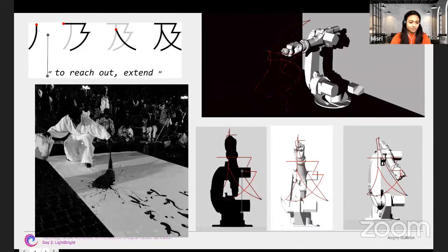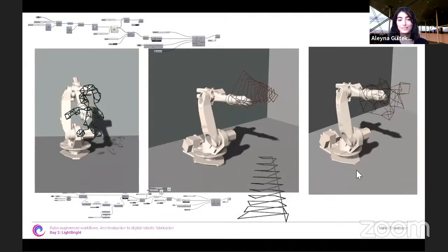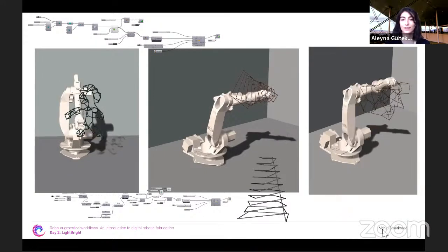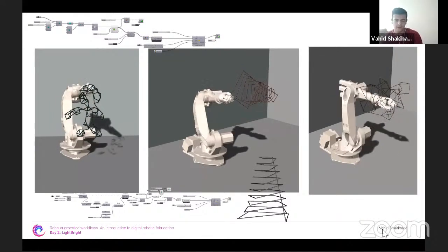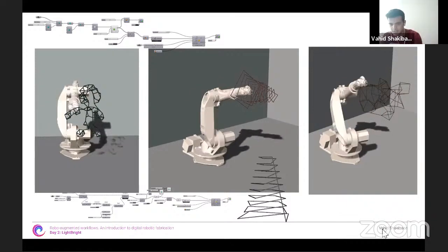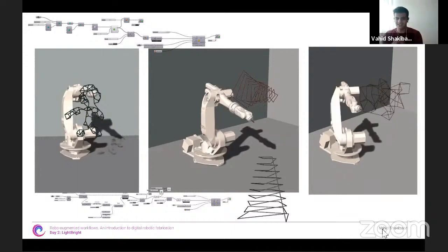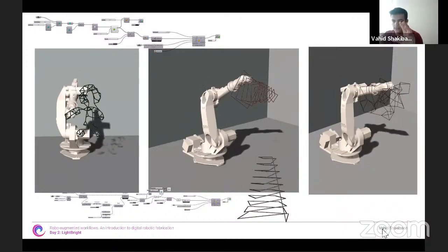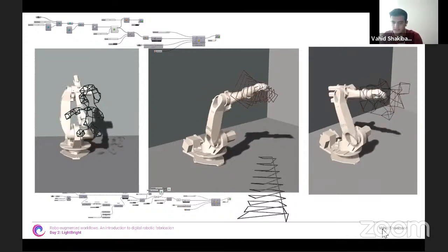I don't know if we have, is that Vahid? This work is mine, and I started my work from the simple shape in the right image GIF. I create a box and use Populate 3D for random points, and then I use the Voronoi 3D.